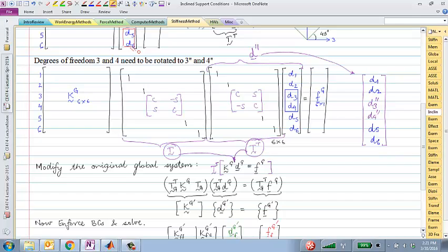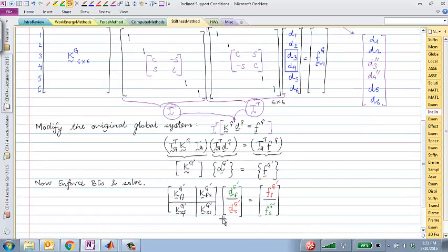So using this, we can express that as a modified stiffness matrix, that global vector, and just to be consistent with that, I'll call this DG prime as well. So this is DG prime, and on the right hand side I have T transpose times F, which becomes FG prime, and we get a slightly modified system of equations which we solve exactly the same way by splitting it up into free and specified degrees of freedom.